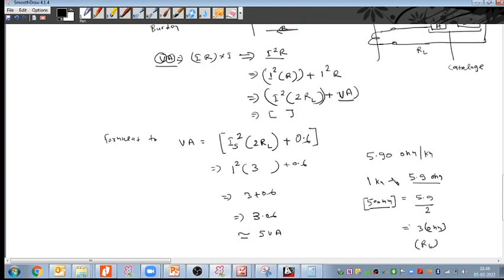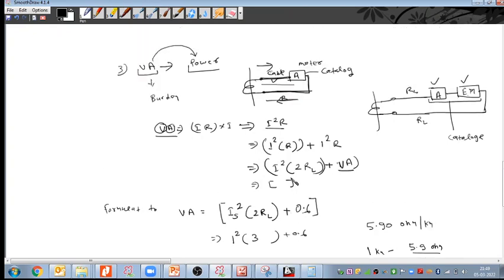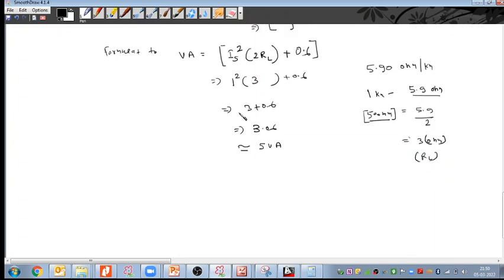I have seen sometimes that in some calculations we also use the CT internal resistance, because we are putting the winding here, so the CT winding will also have some resistance, that we can say the CT resistance. So I have seen many times, in order to calculate the CT burden, some engineers, some companies follow this formula.